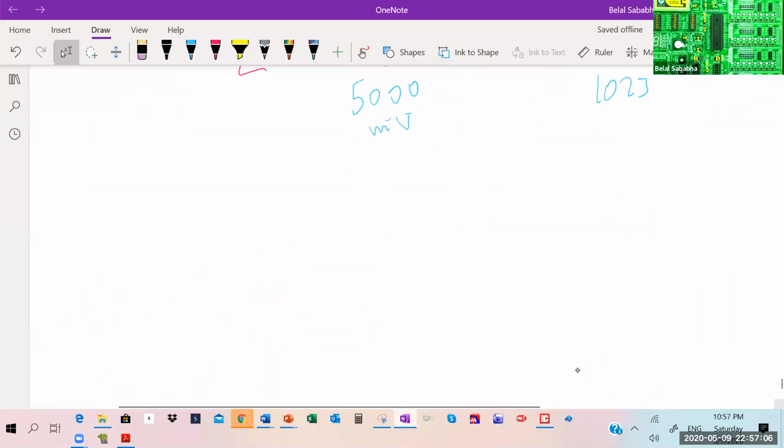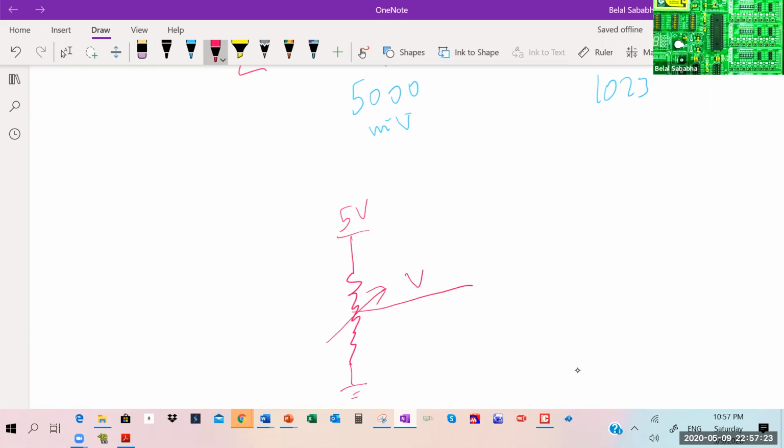This is what we're gonna do. And pretend the potentiometer in this case is the sensor, right? So the potentiometer is drawn roughly here. Okay. It's a resistor, a variable resistor in the end, right? We connect it to 5 volts and I get a V out from here, depending on how I turn this potentiometer. So I connect the top and bottom pins to 5 volts and ground, and the middle I take to port A, the analog port. Okay? As I turn it, this value moves between zero and five, right? And I want to know now whether this potentiometer is an analog temperature sensor, a humidity sensor, or an IR sensor. We don't care, right? It's a voltage. Once I know the voltage, I use the data sheet formula to convert it to temperature, humidity or distance.